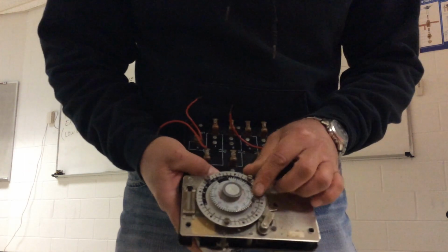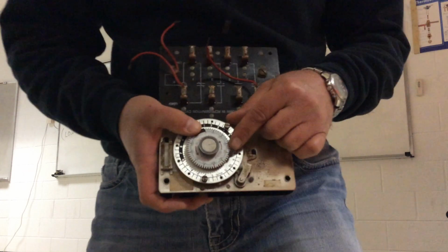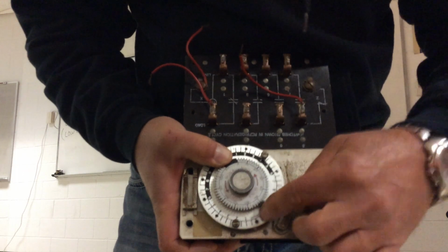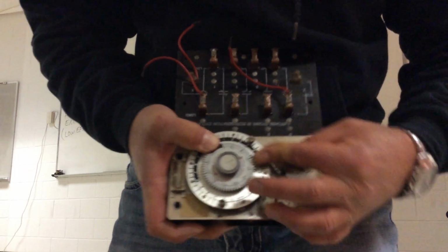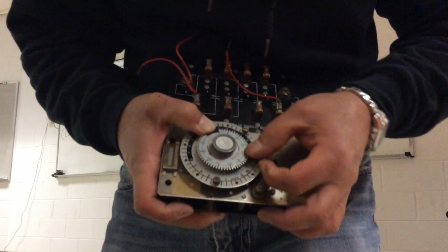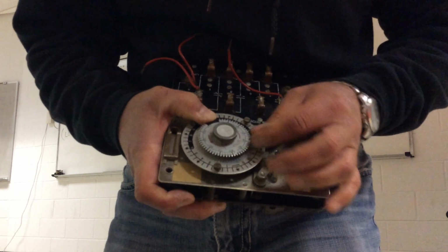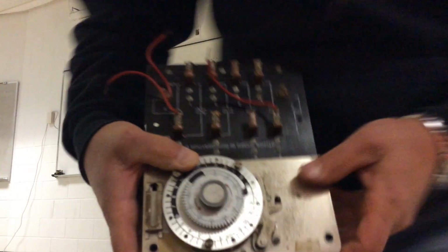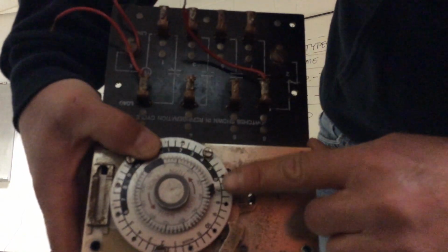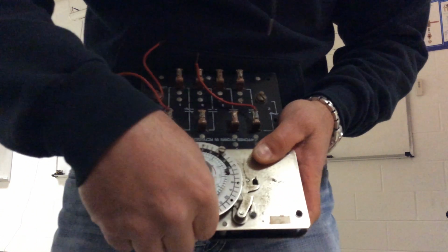Now, I've talked about a fail-safe on the time, and it's usually set at 40 minutes. Right here is a little push-button tab. I can push down on this arrow and move this, and this would be the fail-safe, how many minutes it would actually stay in the defrost. And it locked up right there. But that should be around 40 minutes.